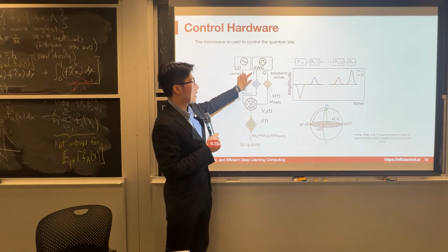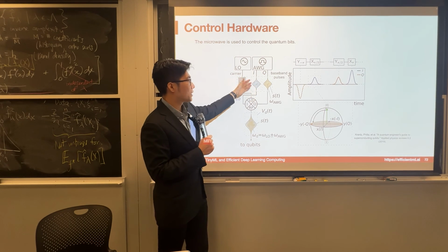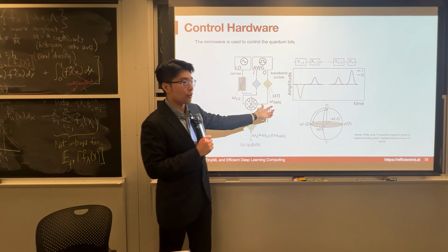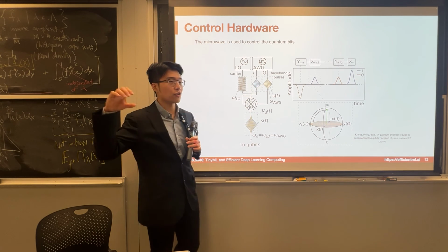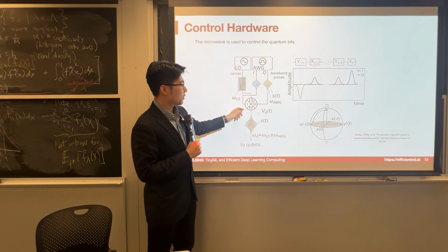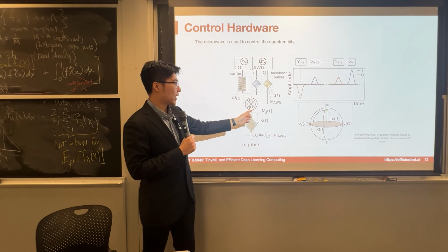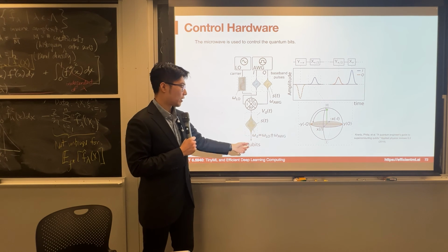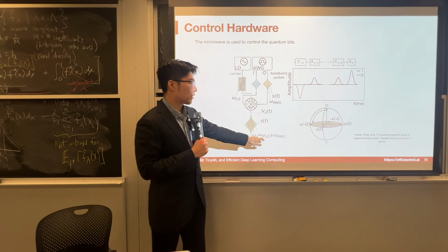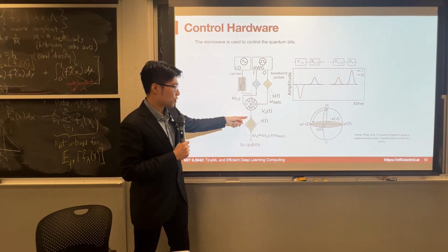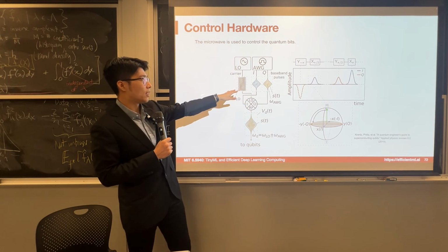And then we also have the arbitrary wave generator to generate the actual control shape. Sometimes it's an envelope. Sometimes I also have a small frequency, omega AWG here. And we also have the ST as the envelope of the control shape. Then we have this mixer to mix this basis frequency with this generated pulse signal, so that we can obtain the desired qubit control frequency, which is omega IO plus or minus omega AWG here. And the envelope will be the same as the baseband pulse envelope.